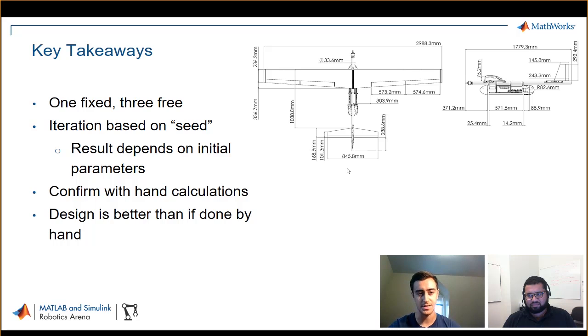There are some texts that state that the wing and tail moment arm distance, so the tail moment arm is the distance between the wing quarter chord and tail quarter chord, should be around 60% of the fuselage length, so the total length for this kind of aircraft. So we just settled on a value around there and stuck with that, because we were finding that running the code with that totally free, it would bottom out on one side of the range. It would either choose the absolute top value we gave it or the absolute bottom value. So I think we had incorrectly defined the parameters of the equation. But once we fixed that, it was totally fine.